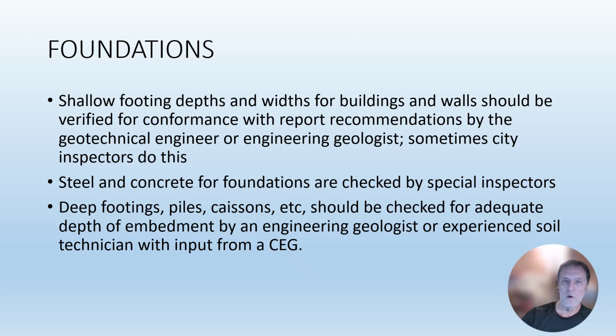Foundations. Okay, so we have a graded pad. We're ready to set a structure on top of the pad that's underlain by compacted fill or formation, pure formation in some cases. So you have to verify depths and widths, verify they conform to the report recommendations.